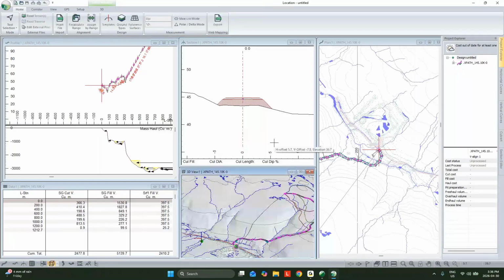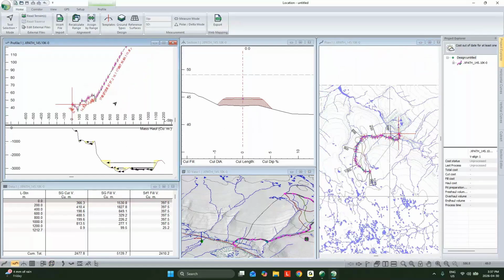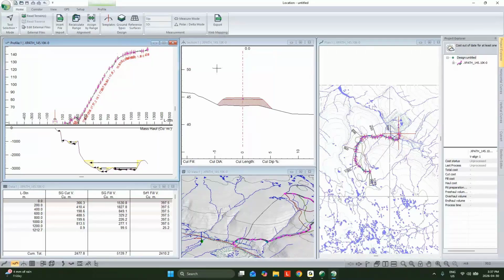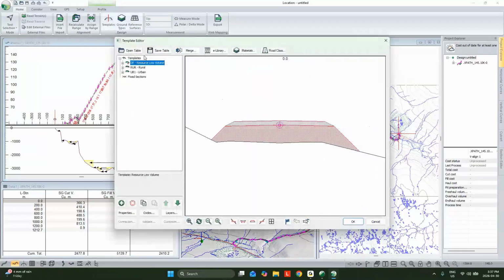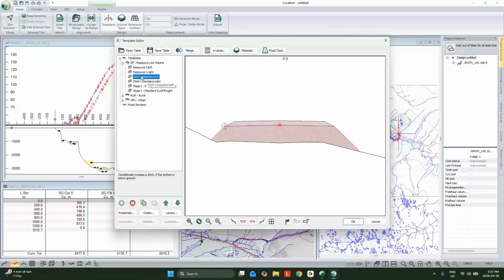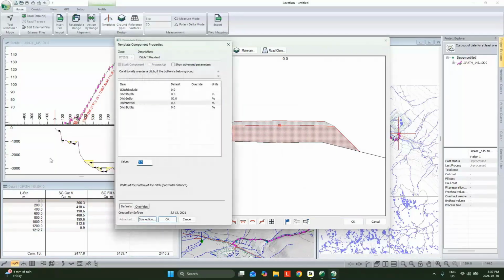And there we are. And this time, since I had saved that screen layout as my normal, when I start the software on a new project, it appears the way I'd like it to appear. So we can see we're going up the hill, we're adhering to our max grades. Our cross-section geometry, now again, I could have saved this too, so it appears the same way. I didn't, to give us that apples to apples comparison. We'll set our ditch to be a V-ditch.